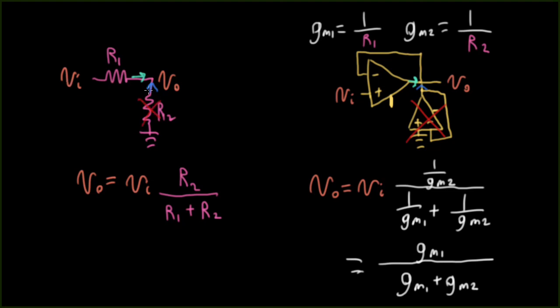So I have my input voltage and my output voltage just attached by this resistor here. And if the circuit isn't loaded down, well, there's no current being lost across that resistor. So, hence, unity gain, with gain in quotes.